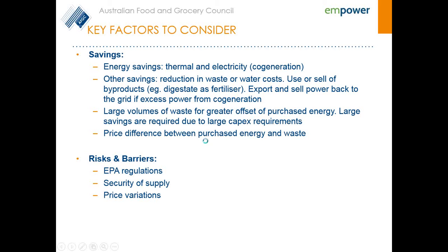Is cogeneration an option? If you don't have a cogen and you're already paying high electricity prices, then it probably makes sense, if you think about generating biogas to fire a gas boiler, to maybe consider putting in a cogeneration unit that can offset some of my purchased electricity or reduce my electricity demand charges.